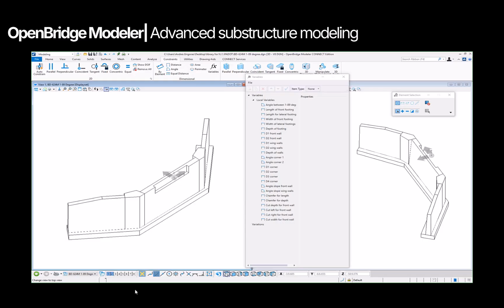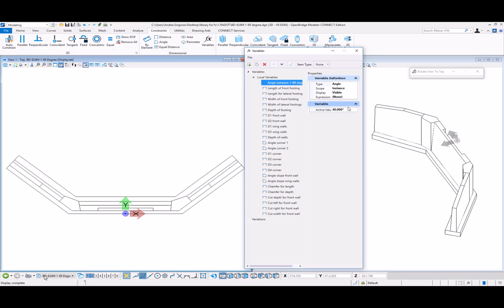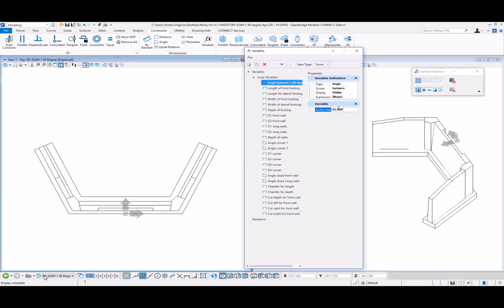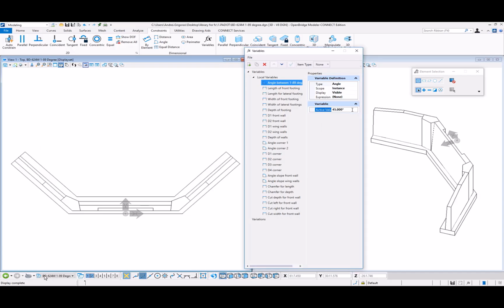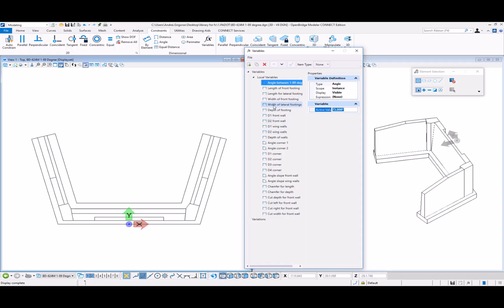Applying these variables, we can model almost, if not all, kinds of piers or abutments and customize their behavior. Using variables, the behavior of the abutments, the wing walls, the hinge or corner block could be fully automated depending on the case. That could be because of the superelevation, or because of the skew angle of the abutment, and so on. So lots could be done there.